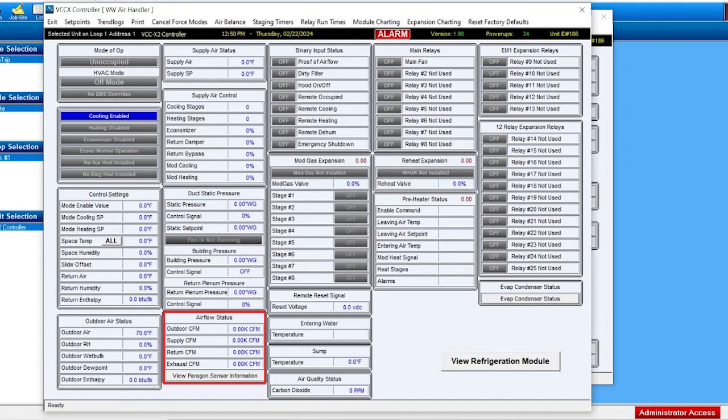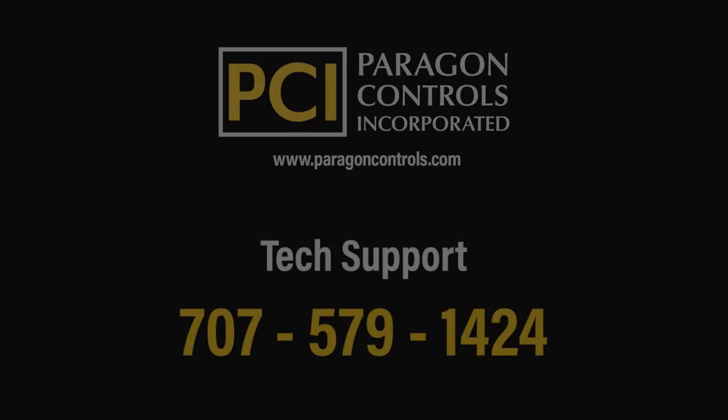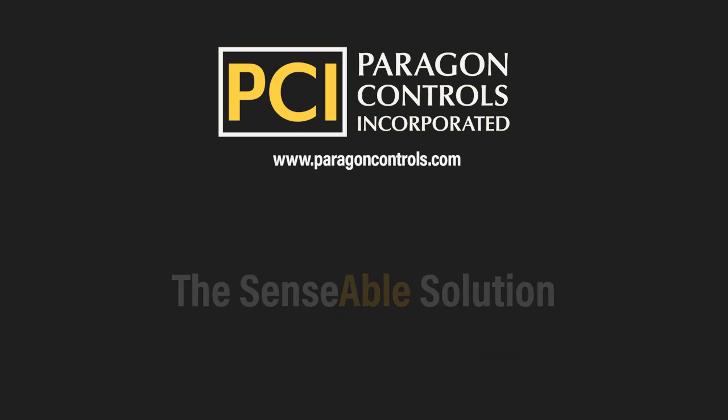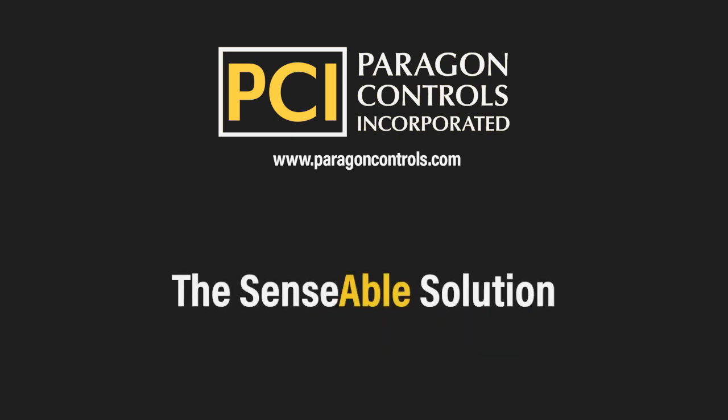Return to the Details Viewer page to ensure flow values in the Airflow Status match the values as shown on the AMTSE display. If these values do not match, please contact our Tech Support team for additional assistance at 707-579-1424. Paragon Controls, the sensible solution.